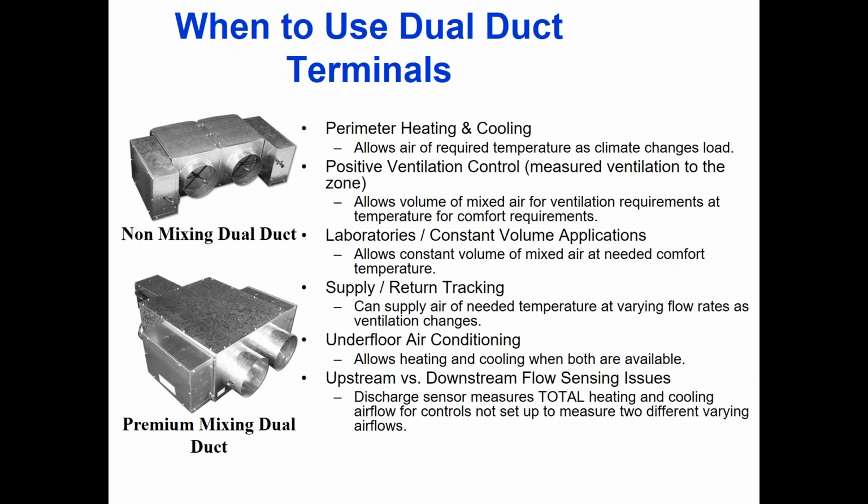All right, dual duct. This is also not a common one, but it's a lot more common than retrofit dampers or bypass dampers. So dual duct means you have a special air handler that simultaneously makes hot air and cold air. It has two different decks. It has two different airflow pathways, right? So there's a return fan coming in and a supply fan going out, and there are two different airflow paths, one for a hot water coil and one for a chilled water coil.